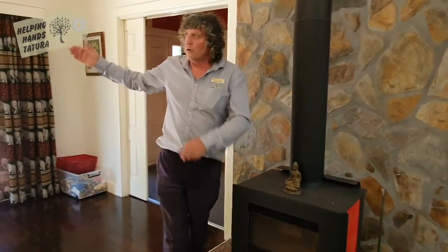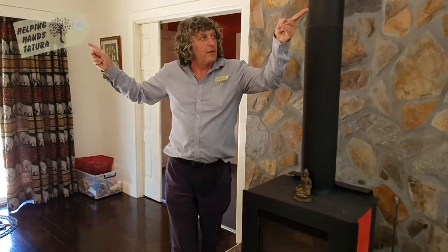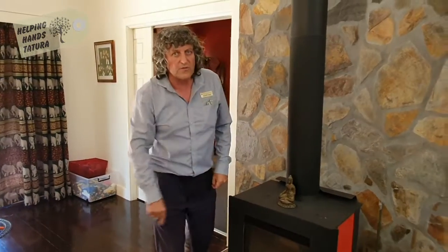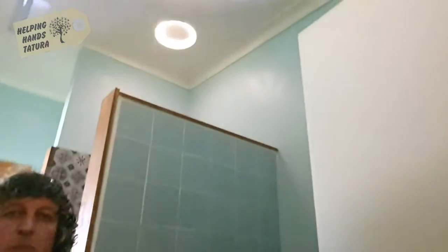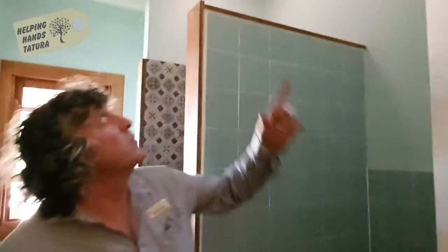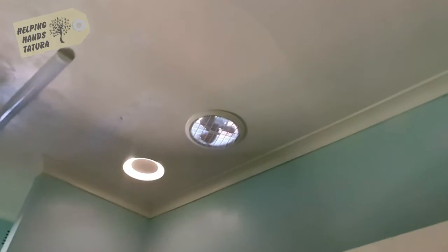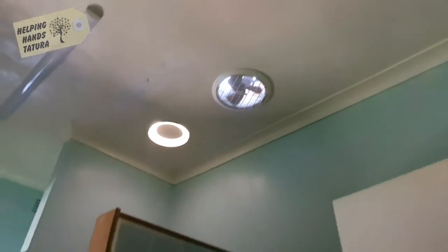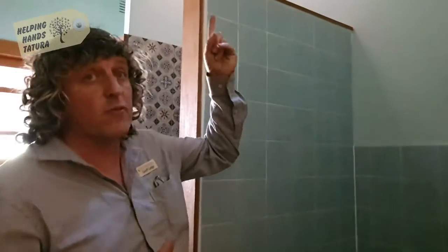And with the blinds drawn, the pelmets, the air vents sealed, the draft stop on the bottom of the door, all of that will help retain much more of the heat overnight. So again, we're looking at where are the weak points in the house in terms of unwanted heat loss, heat gain. And exhaust fans, as we're looking through here, we can see that is a permanent opening, a permanent leak, and the exchange of heat in winter will be escaping constantly, 24/7, being sucked up through there and lost.